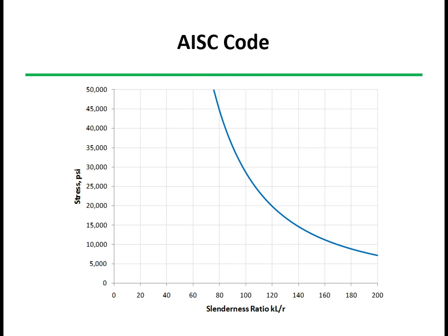So based on that, let's go back to our curve a little bit, starting with the theoretical buckling curve. And remember that our yield strength is at 36,000 psi. So if we take half of that and find the slenderness ratio that corresponds to that, that's the number we calculated as 126.1.